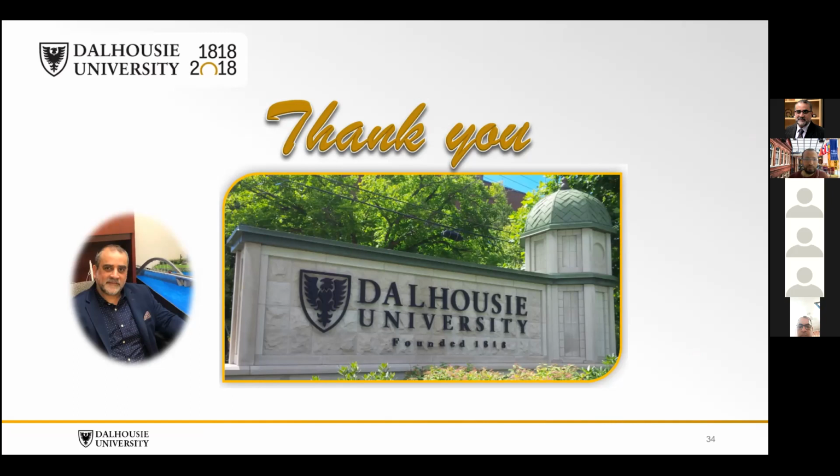Please. The first question is related to the forces applied to the tunneling in the first part of the presentation. I observed that you applied a drilling pressure during tunneling, but I'm wondering if different forces were applied to the tunnel. So for the tunnel face, you have a face pressure which is linearly increasing with the depth, of course, to resist the pressure from the soil.